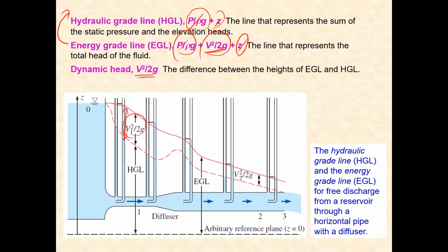So you can see here from the left that there is a venturi, where we have a wide opening to a narrow opening, and then it's diffused into a wider opening. So from here to here, where you have a wide opening to a small opening, you can expect the velocity to increase. Here, the dynamic head is zero because the velocity is insignificant and can be neglected, considered equal to zero, and then it increases.